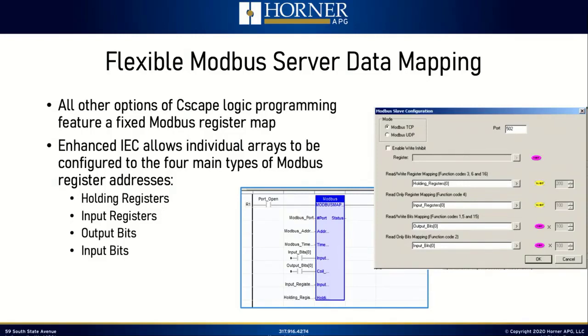As long as you remember to move over, using move commands and other things, the actual machine data that needs to be reported. If you've got a machine and you want to report temperature and pressure, etc., you not only need to create the arrays to report the Modbus data back, but you need to remember to copy over the temperature data and the pressure data into that array so that it'll get reported properly.